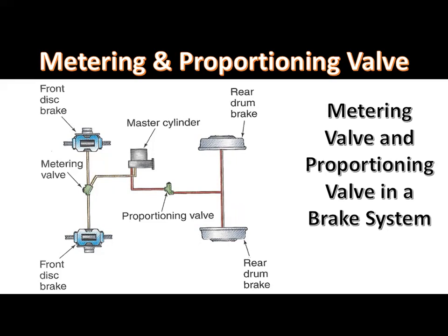During a brake application, vehicle inertia and momentum tend to shift the vehicle weight forward. This weight shift is proportional to braking force and the rate of deceleration. This weight shift reduces traction between the rear tires and the road surface, which may result in rear wheel lockup.